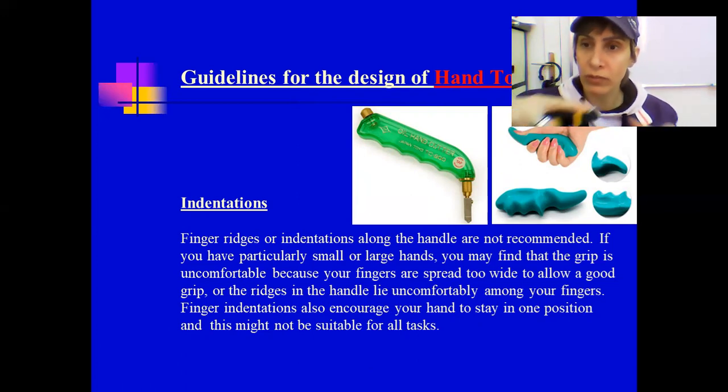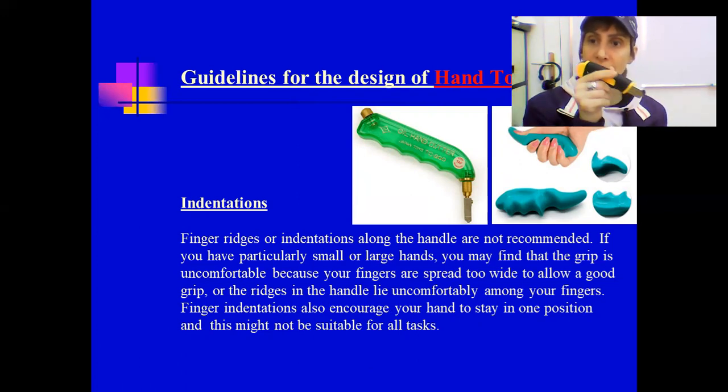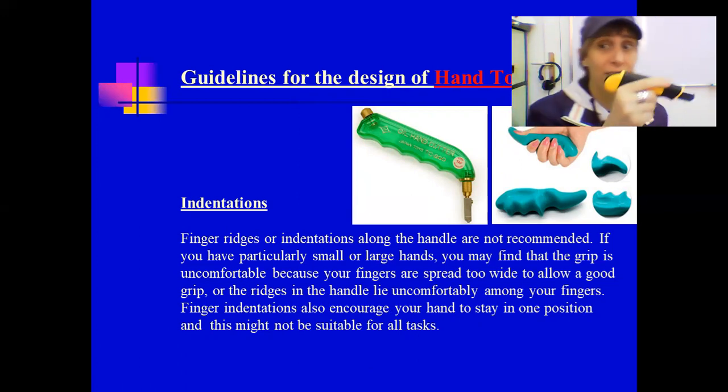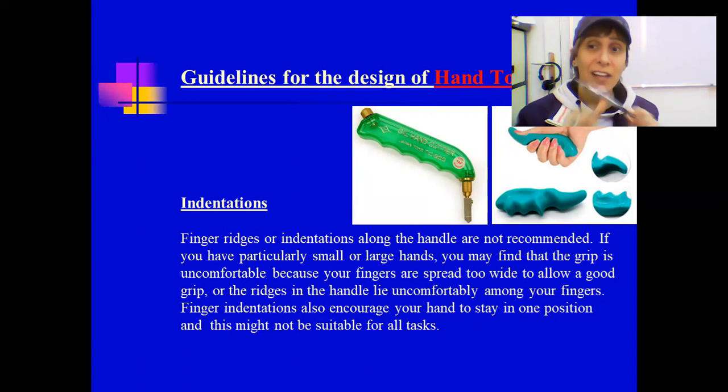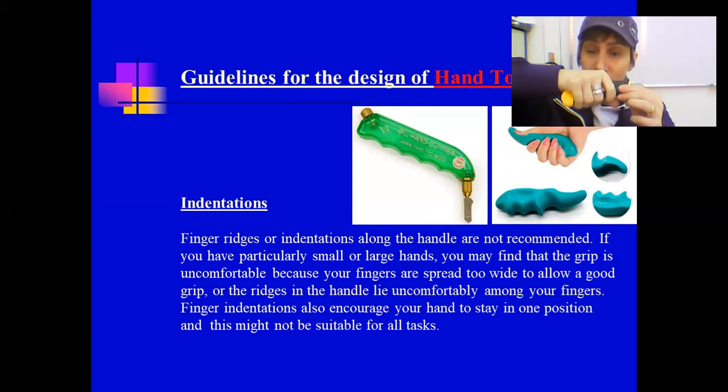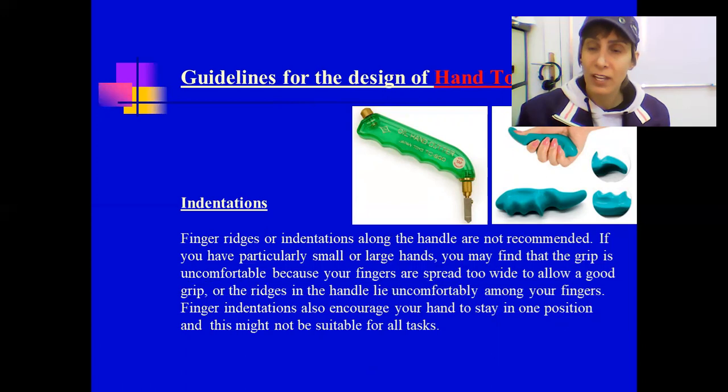Not like some students cut, I've seen, holding it like a pencil. No, no, no, no, no. This cutter should be used with the whole grip and finger here, not like this, okay?